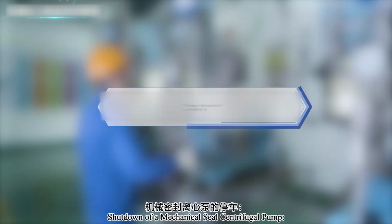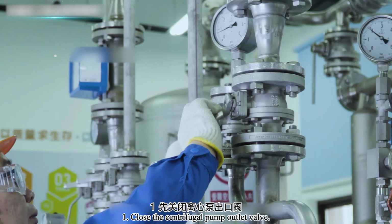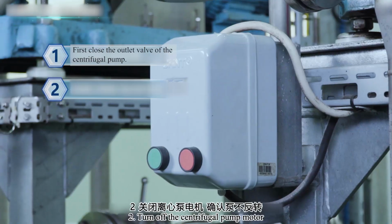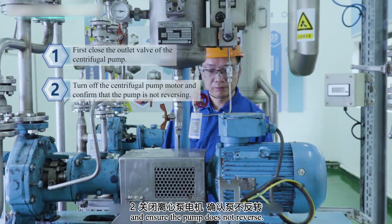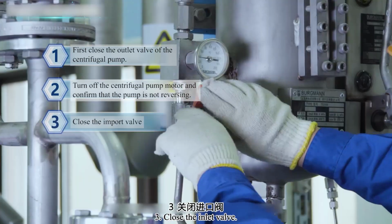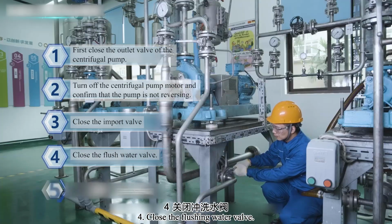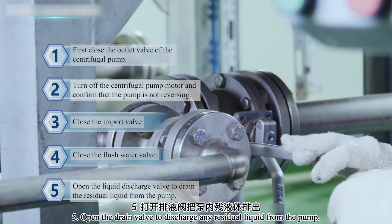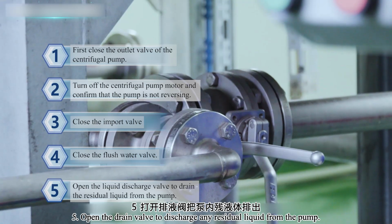Shutdown of a mechanical seal centrifugal pump. First, close the centrifugal pump outlet valve. Second, turn off the centrifugal pump motor and ensure the pump does not reverse. Third, close the inlet valve. Fourth, close the flushing water valve. Fifth, open the drain valve to discharge any residual liquid from the pump.